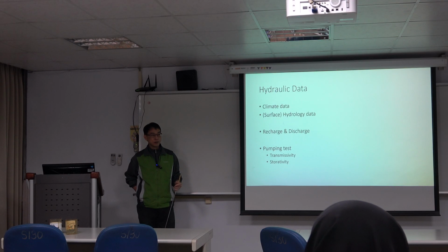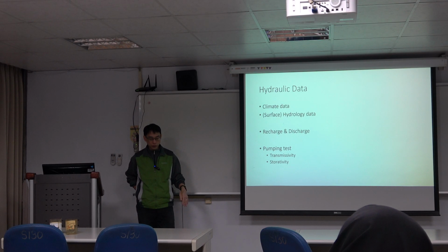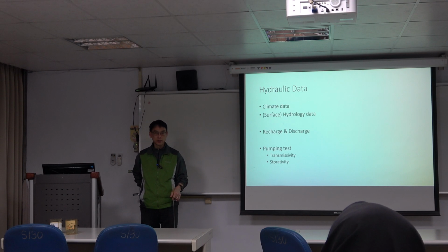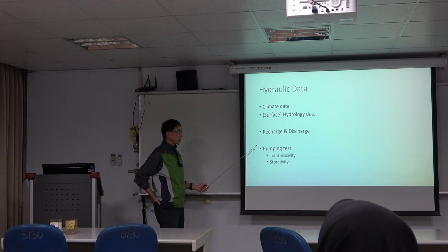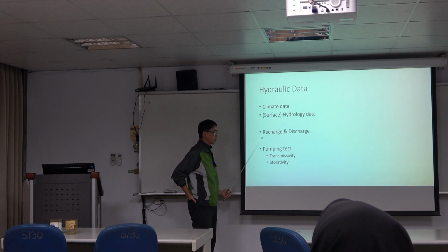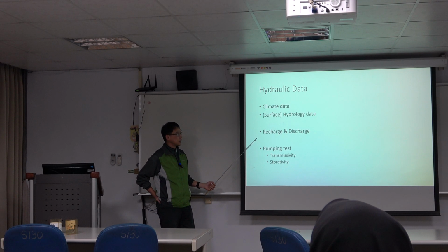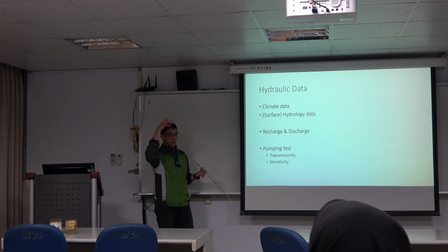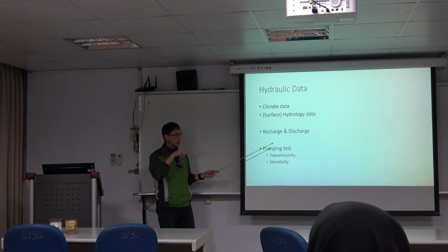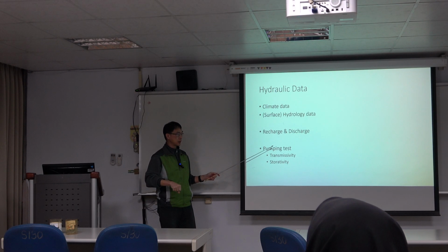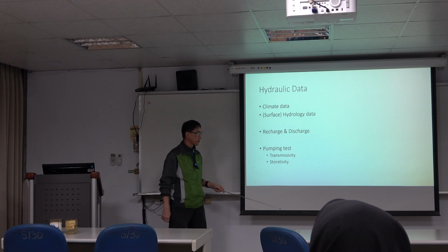Okay, so in the next lecture we're talking about from the mountains to the plain for the groundwater system. How the mountain waters flow to the plain area to recharge your groundwater system is a very important issue together. So commonly, from what we call the boundary concept, there could be recharge and discharge outside. And for the inner part, we might have another recharge. Sometimes we use the managed aquifer recharge concept, artificial recharge conditions. Another could be the discharge pumpings.